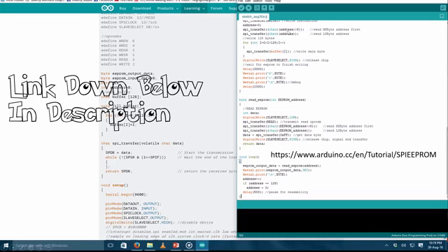So what is happening is that we first transfer our address by the SPI transfer. And over here, if you want to read from the EEPROM, you put your slave select down to low. You transfer the read opcode or the instruction code. And over here, we have it as read. Thereafter, we send our address that we want to read from. And then this is the data that we receive. So SPI transfer, which goes into data. And then we return our data back for use.